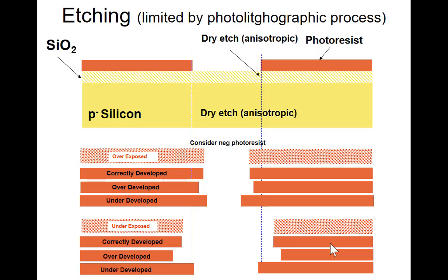And once you have your masks after this processing, after development, you could get a different line width here. And then in the etching part, some of these would also get etched away by the acid. So from this example, you can see that when you draw something in your design, and then after you fabricate, what you fabricated may not be exactly what you want.